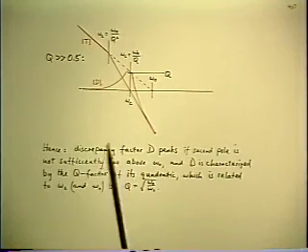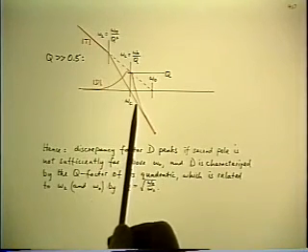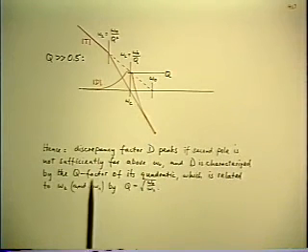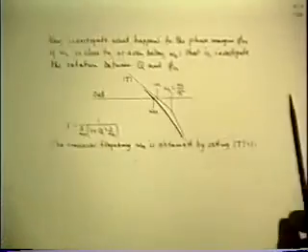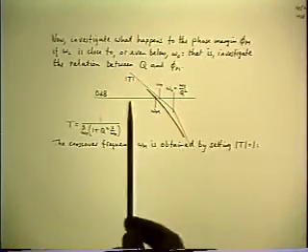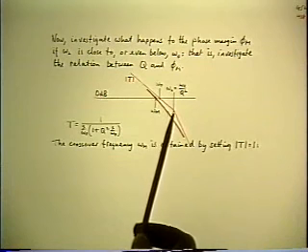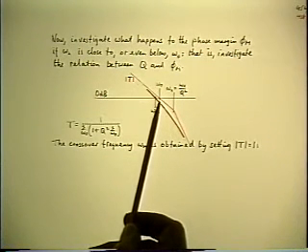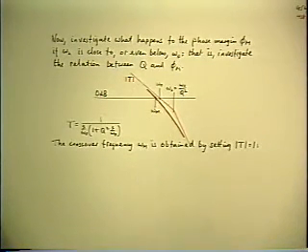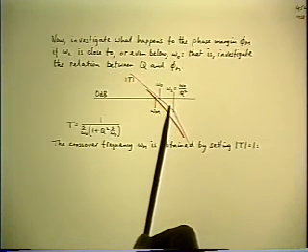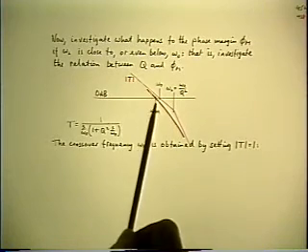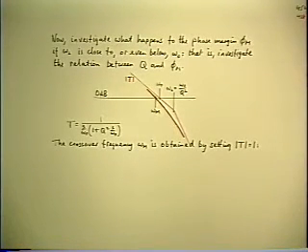So far I've just asked you qualitatively at each case what's the phase margin, but we can actually get a quantitative result. Here's how we do it. Here's the general case, where I've drawn the second pole in T a little bit above the original crossover at omega 0. All I have to do is calculate the phase margin using its definition. The phase margin is defined in terms of the phase lag of the loop gain at the crossover frequency.